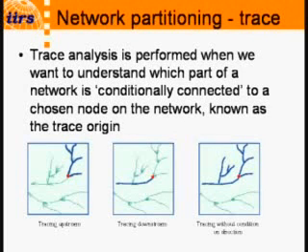So you can even draw a point over here. Automatically it will show you what all channels are contributing to the output or the outlet of this particular thing. So you can use this trace analysis in various hierarchical modeling, and this is very important. Flow accumulation and flow direction are examples of trace analysis.